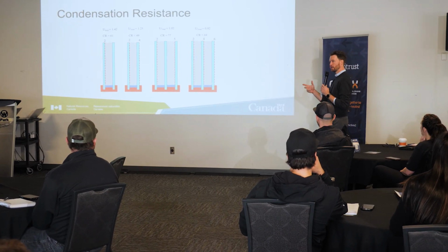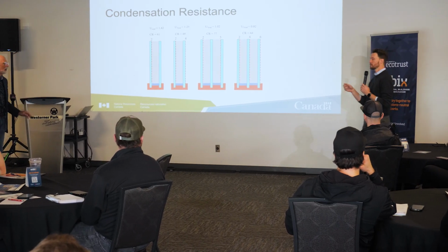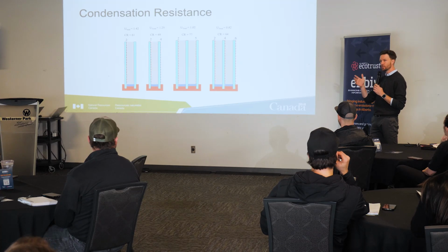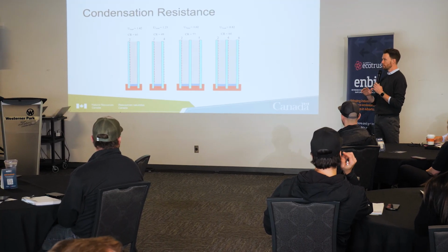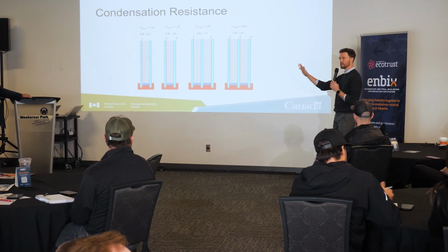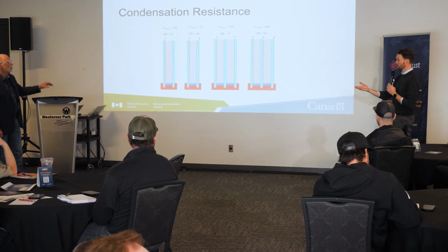I think we have a handout that you'll be able to pick up down at the build booth after the show that has some answers to those questions. From memory, I think anything 65 and higher-ish in condensation resistance should make you sleep very well at night. But I just wanted to highlight that we see differences in numbers all the time. But it comes back to what questions you're going to ask your manufacturer, your supplier.